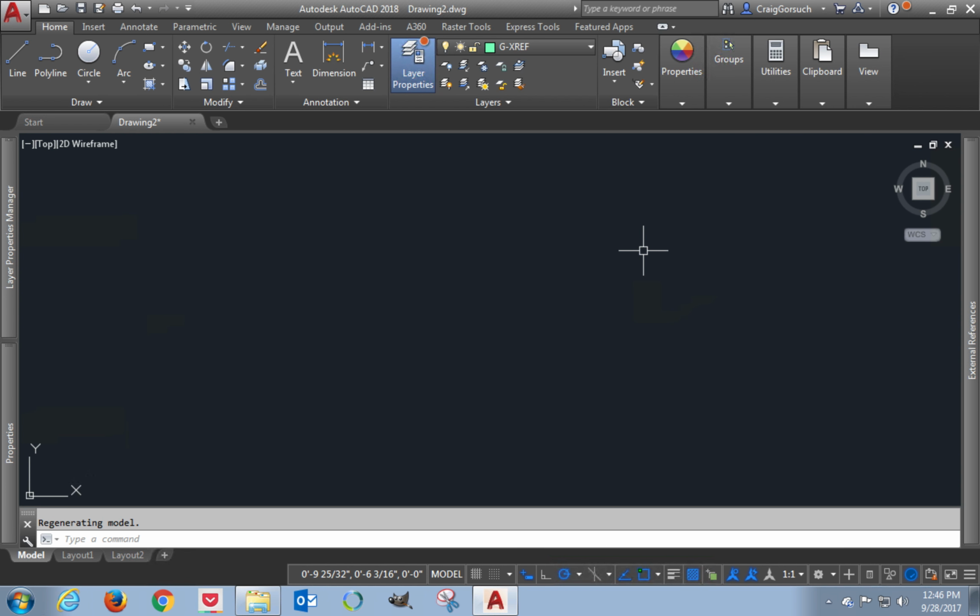That's because my insertion, when I did the left click drag and drop to get my floor plan file in here, creates a block of A101. I cannot reference a file A101 that I'm using as a block. So the only way to fix this problem is I have to type U at the command prompt. So I'll undo, and it says undo zoom. Press return again. Undo group. That's probably my XREF command.